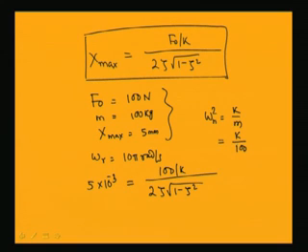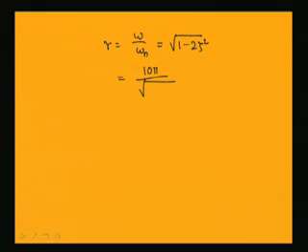I know the relation between r and zeta for maximum amplitude. So, r equals omega by omega n, which is equal to root over 1 minus 2 zeta square. Already you know that maximum amplitude will occur at this frequency. So, omega n is root over k by m and omega is known, so this is equal to 10 pi by root over k by 100, and it equals root over 1 minus 2 zeta square.